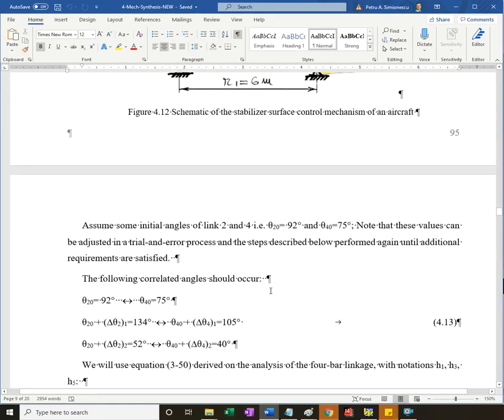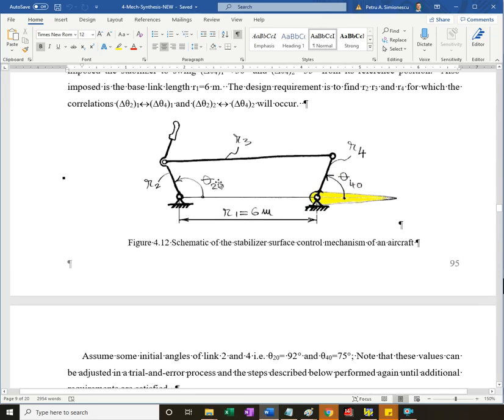And there's a numerical example. You have the freedom to choose the fixed angle here as well as this one, right? You can have this lever sticking at different angles off the control surface, and you can bend the actual pilot stick. This one goes between the legs of the pilot. Not all aircraft have this kind of control. The smaller ones do. Fighter planes are the same. Commercial airliners have a different means of controlling the surfaces.